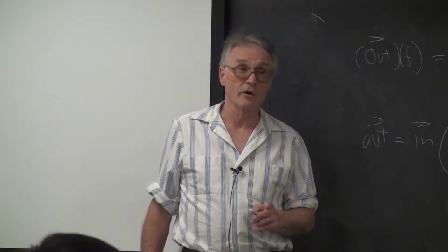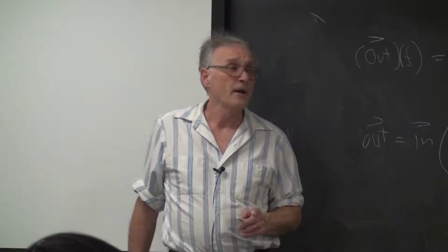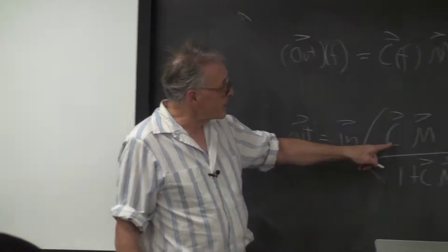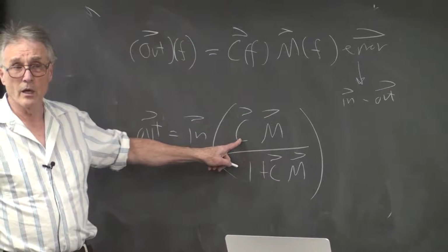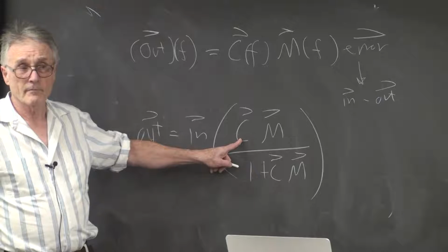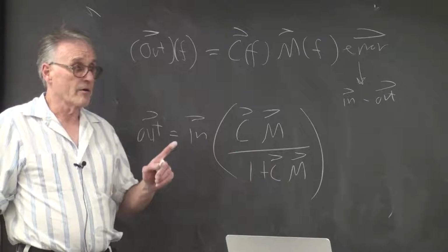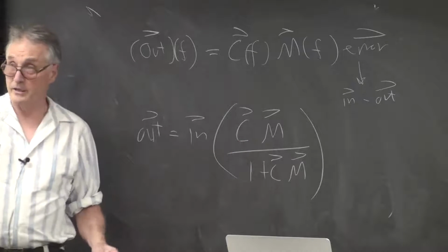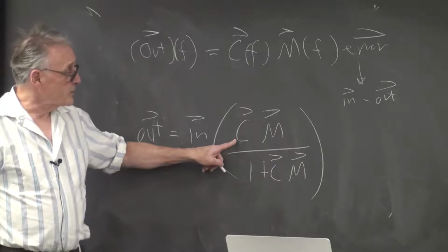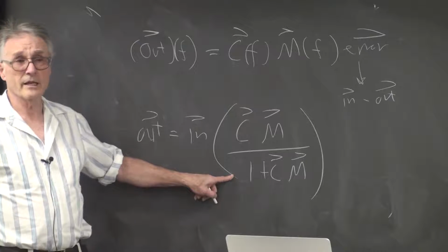You'll get changes in the wrong direction, which are very big. So merely increasing the size of C to lower the error doesn't work very well. However, it is completely true that if C is a scalar value, a constant, the larger you make C, the lower the static error.